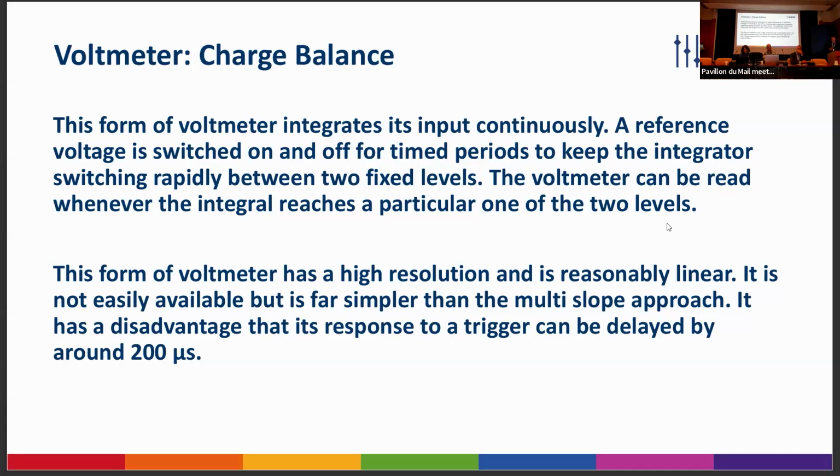As long as there's no energy in the signals at those frequencies, then a few hundred microseconds of trigger error isn't actually going to change things at all. Also, anything that you don't measure in one period goes through to the next one. It never stops integrating.